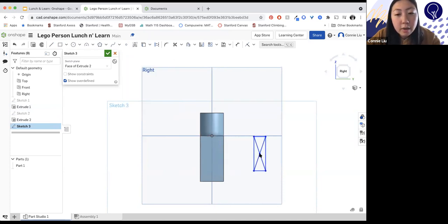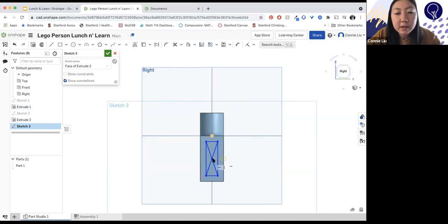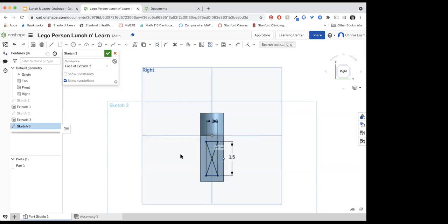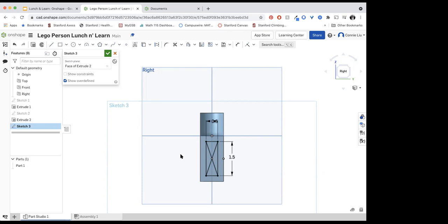Do you see how I'm able to drag this around from the point I created? When I drag it closer to the middle, it just snaps in to the middle because there's another point associated with it. I had converted my lines into construction lines before adding the point, so maybe that could have been it. Maybe. I don't think that should cause that issue. And you definitely have a point already in there in between the construction lines. So strange.